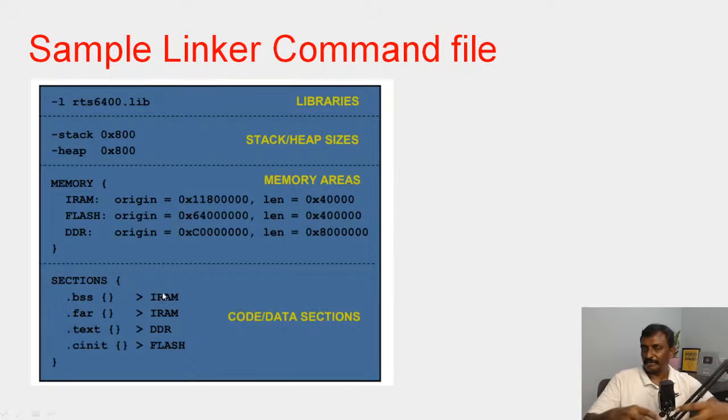This code is different, it is not C language. Every manufacturer comes up with their own type of syntax, but you could grasp it within one day. If you go through the linker script, you could grasp it within one day, not even one day, like 1 or 2 hours. If you go through the sample linker script, you could change it and see the results, but the concept is the same.